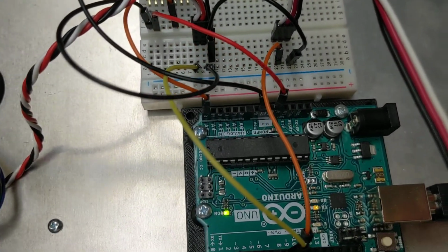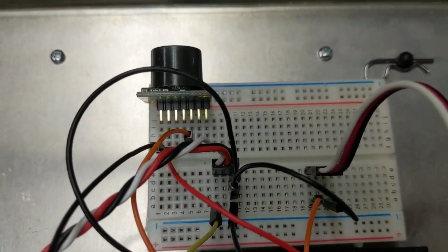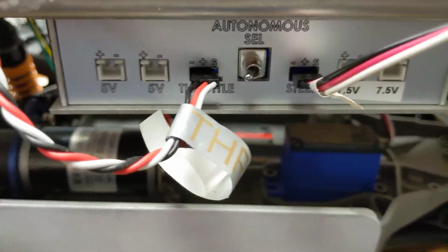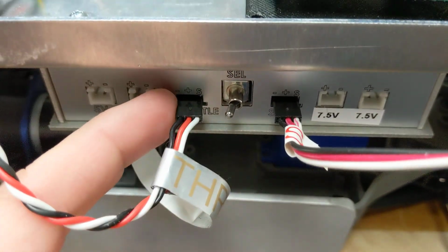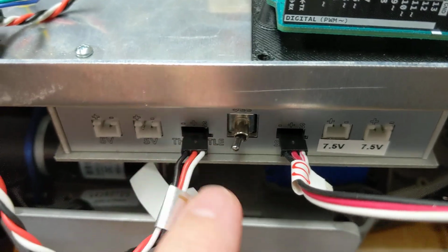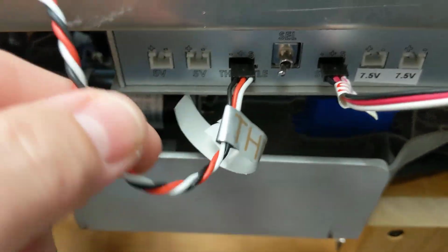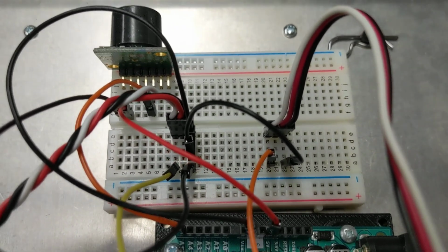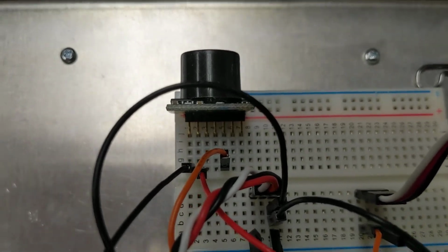Channels 9 and 10, right, are my 2 servo channels, and those are going to the steering and throttle on the side of the vehicle, right? So this is just, negative is ground, positive is power, and S is signal. Do not connect power to this. So simply, I'm just jumpering power and ground. And then the last piece, I am providing power, ground, and my analog signal.